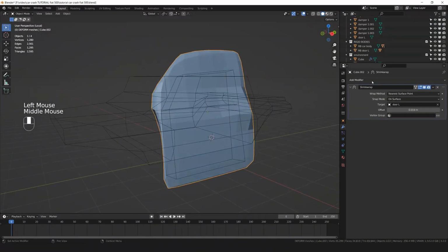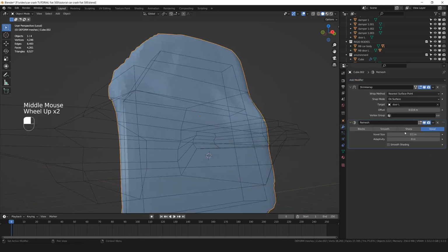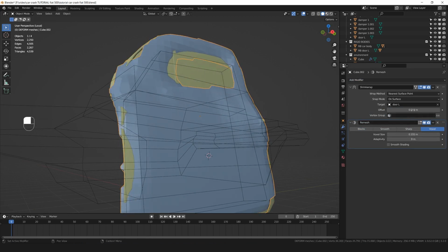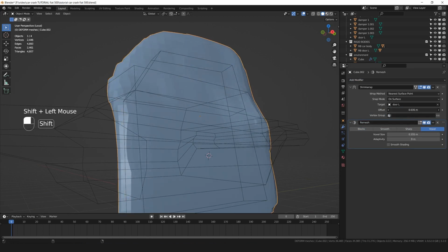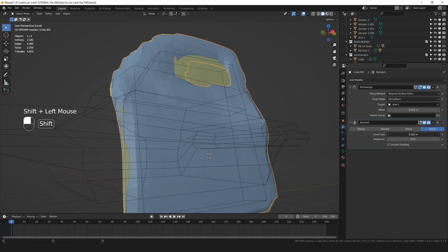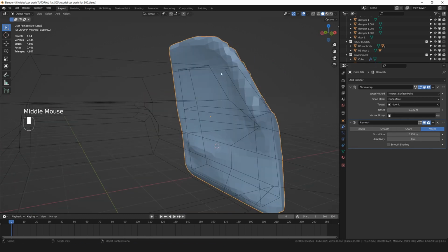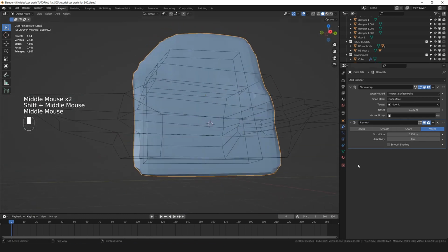And again, I'm gonna apply the remesh modifier, without exaggerating with the geometry. So try to increase the voxel size to something like this. But I want to push more outside the shrink wrap, something like this. Alright, and a little bit smaller the voxels. We don't need a very high amount of geometry for the door. So just tweak these options for the shrink wrap and the remesh until you find that the mesh is fine. So something like this to me it looks good.